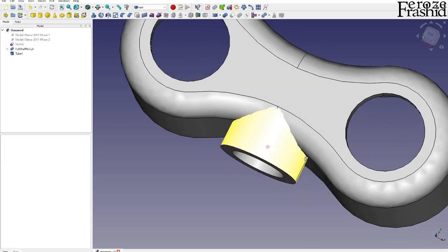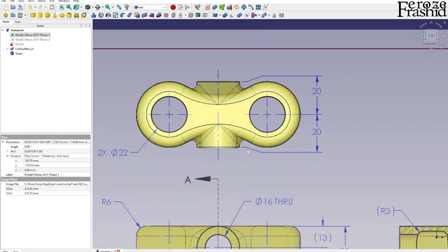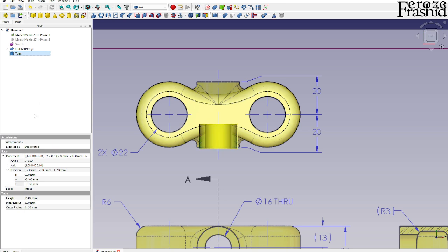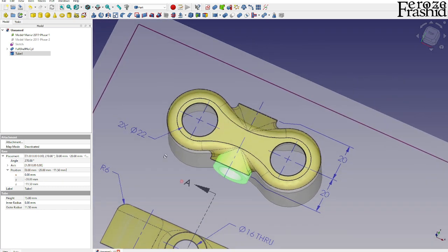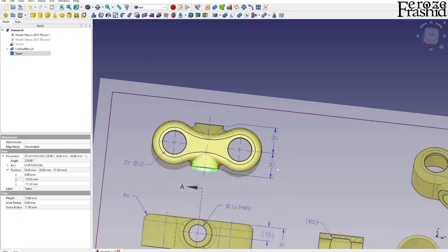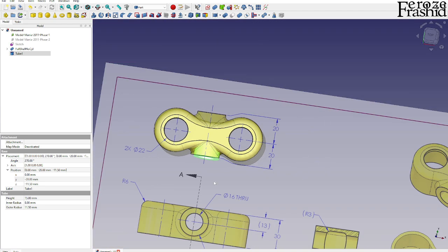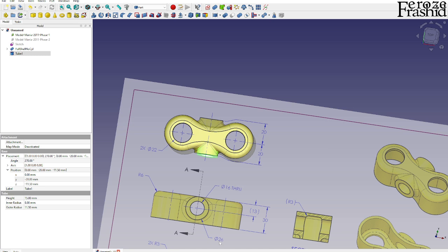All right, because I see that this edge is at 20 from the baseline, so now I can go and see on the y it is minus 21. Let's make it minus 20, so that actually places it right where I want it to be. And then I see the diameter is not matching up. This line looks a little smaller, so this outer diameter is 26, so radius would be 13, right?